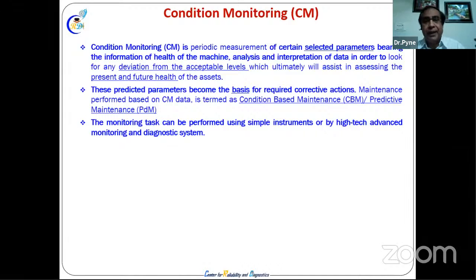also develop in different ways. If it is vibration, we take a vibration instrument and its processing systems; you call it vibration monitoring systems. If you take temperature or thermal imaging, you take that as the sensing part, then you analyze, and the entire system you make it a thermal imaging system, a different condition monitoring technique. So ultimately, certain selected parameters we measure.